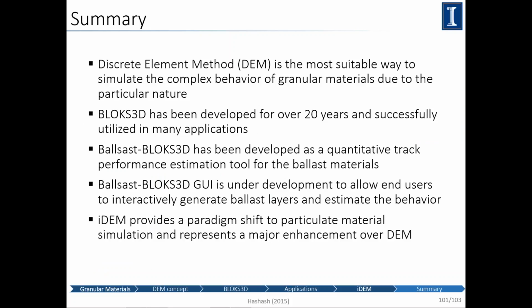Okay, so let me go to the conclusion, and we'll have some discussion on this. Discrete element is the most suitable way to simulate complex behavior of granular material. We have been developing BLOKS3D for 20 years, successfully utilized in many applications. The Ballast BLOKS3D, the one with the user interface, now allows for track performance evaluation, and it's being, let's call it alpha or beta tested. IDM, impulse-based DM, will provide us with, I think, a paradigm shift in our ability to do particulate material simulation in engineering, because we can run 100 times faster or more.